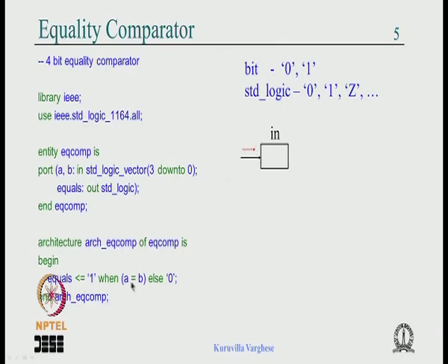In any assignment the input can come only on the right hand side of the assignment. That should be kept in mind. Similarly there is out, which means it is an output port, where some gate or flip flop's output is driving a signal outside, and when you declare something as out, like equals, that should come on the left hand side only.